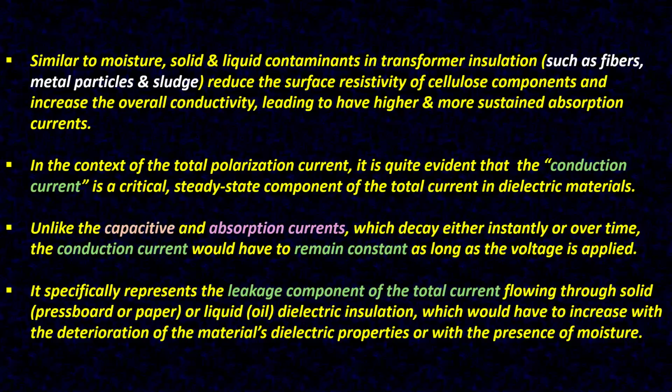It specifically represents the leakage component of the total current flowing through solid insulation, that is pasteboard or paper, or liquid dielectric insulation, oil, which increases with the deterioration of the material's dielectric properties or with the presence of moisture.